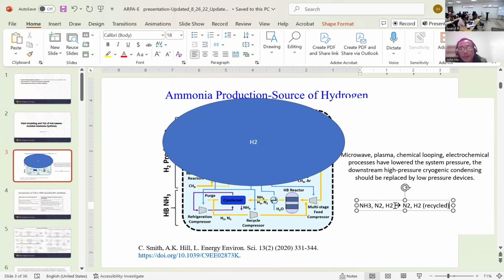What was your size range of the condenser? So basically, this is going to be 250 bar, all right? Yes, sir. 250 bar gas coming out. Now, ammonia has a partial pressure, all right? The ammonia contributes to this 250 bar. Remember, you have three components in the reactor: ammonia, nitrogen, hydrogen. So before the condenser it is still 250 bar. Now after the condenser, you have to compress it. Why? Because ammonia is gone. Hydrogen and nitrogen will not sustain 250 bar, because the ammonia is gone, the partial pressure.